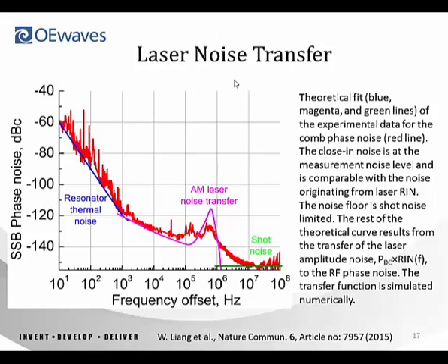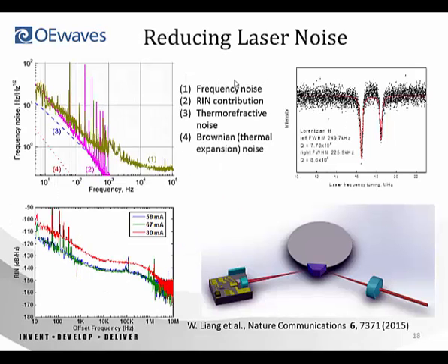We're trying to handle all of them and use a better laser to improve this performance. As I mentioned, to have a better laser, we use the self-injection locking technique, and because of back reflection and back scattering to the resonator, we don't have any isolator between the laser and the resonator. We have line shrink,